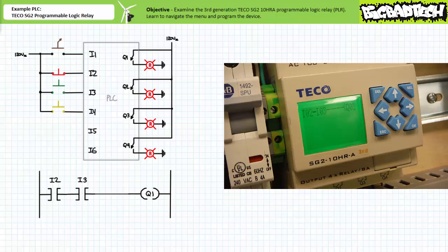Notice when no button is being actuated, the ladder display shows input 2 is allowing logical continuity to input 3, symbolized by a highlighted bold rung. However, input 3 does not pass the logical connection onto the output. The output remains de-energized. When only the red push button is being actuated, the program shows no input is allowing logical continuity. The output remains de-energized.